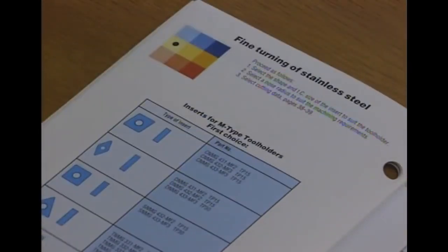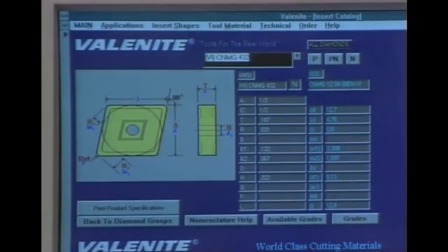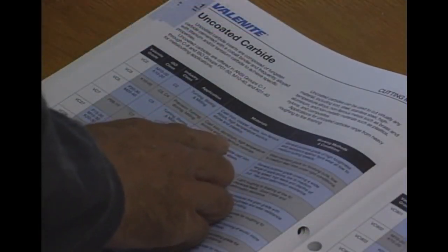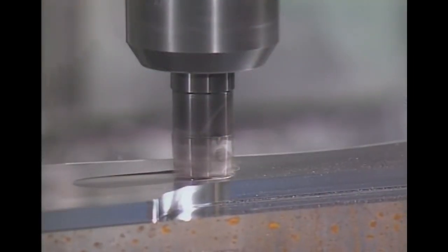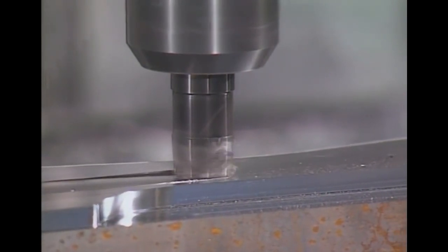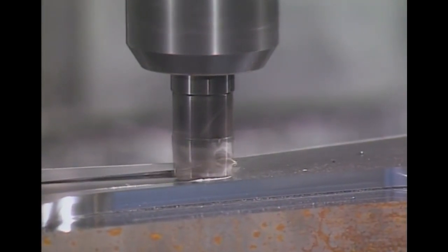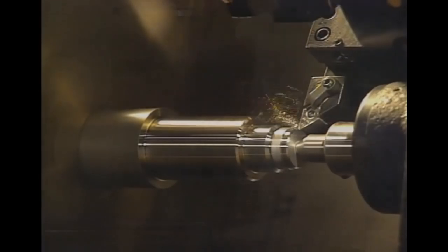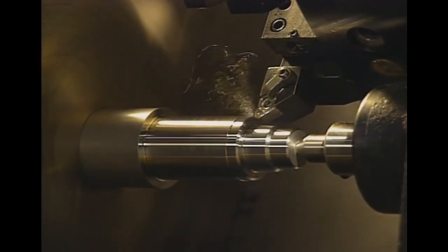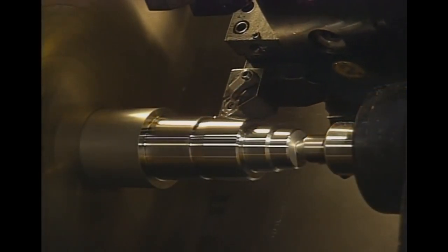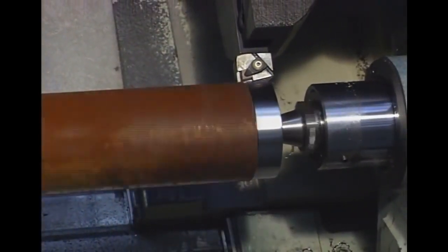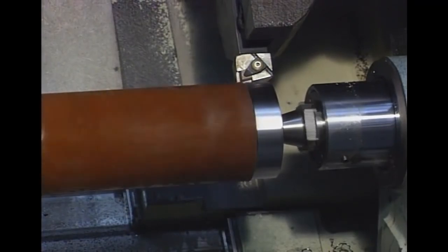Every manufacturer of carbide tools has a variety of carbide grades for specific work materials and types of machining applications. Choosing the correct grade of carbide can double tool life or double the cutting speed for the same tool life. Tough, shock-resistant grades are needed for interrupted cutting. Harder and chemically stable grades are needed for finishing steel at high speed. Heat-resisting grades are needed for machining the superalloys, such as Inconel and Hastelloy.